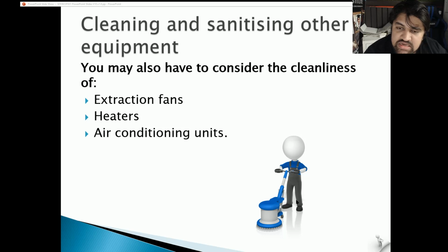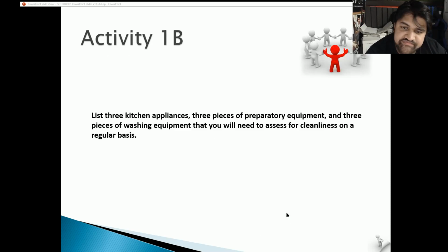So heaters, air conditioning units, you want to clean those filters because they're absorbing that bacteria. You don't want to have them being clogged up. When you have clogged up filters, you also use more electricity. So if you can clean them every 3 weeks or a month, at least once, or at least give them a little brush around so they don't have any fluff or dirt around it, then your machine performs a lot better and you use less electricity, and obviously there's less buildup of bacteria in the machine.